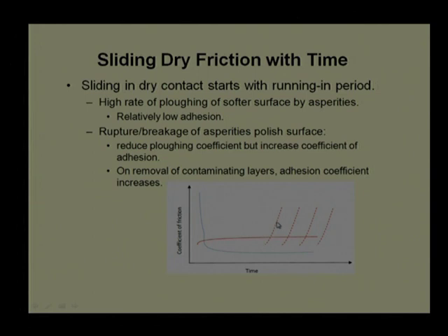It may be, say, similar pairs. One pair can show life starting, coefficient of friction decreasing, reaching a steady state condition, and then again the coefficient of friction increasing. Another, similar component of a similar material pair, in another condition can show reaching this condition, moving to a straight condition, and finally ending with this line. It depends on environmental conditions which line will be selected, or there is a possibility of extended life, or many times we get infinite life. That is also a possibility. It will show the coefficient of friction as a steady value throughout its life.